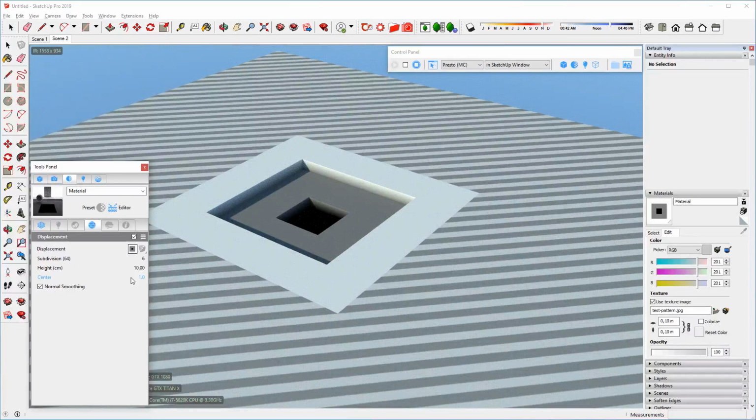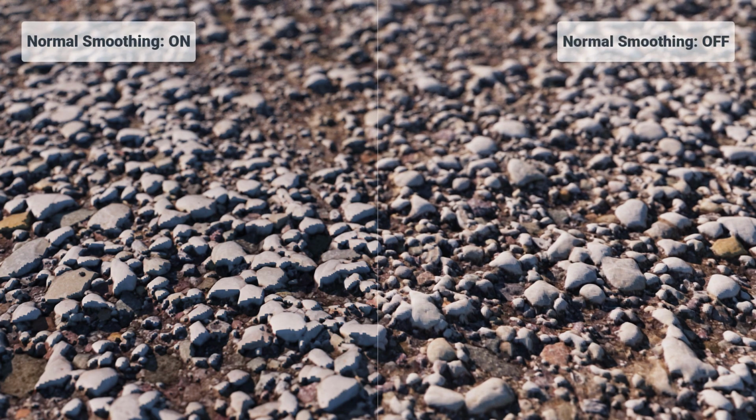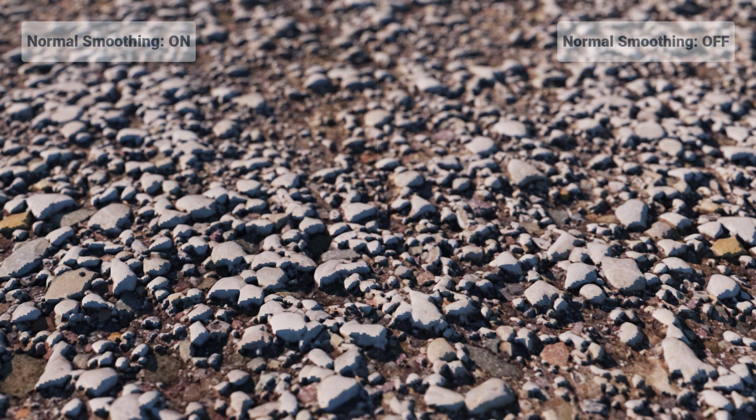This option can be useful when the displaced geometry intersects with other objects in the scene, like a carpet for example. Smoothing should be turned off when the original surface has sharp edges. In any other case, it is best to have this option enabled.